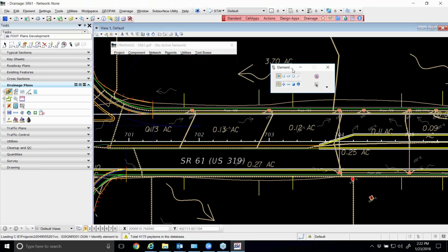As we're having people open that project, if you look on page 6.1, you'll see the definition in the introduction of what GEOPAK considers a network. It's interconnected nodes and links that go to a single outlet. That's the biggest part of it: GEOPAK drainage only supports a single outlet per network. There are other non-Bentley programs that will support more than that.